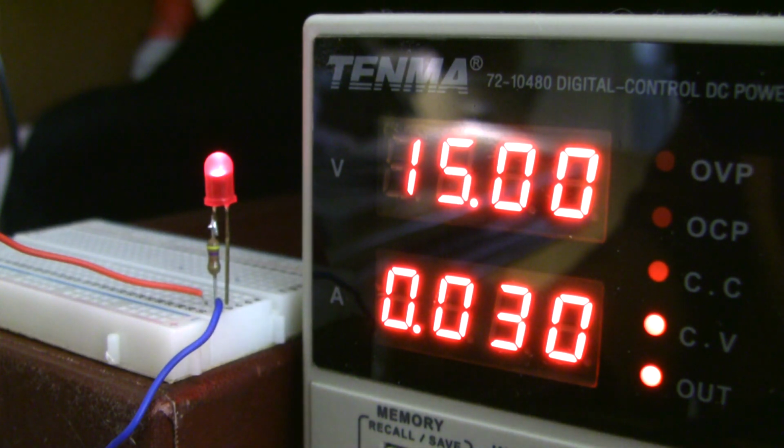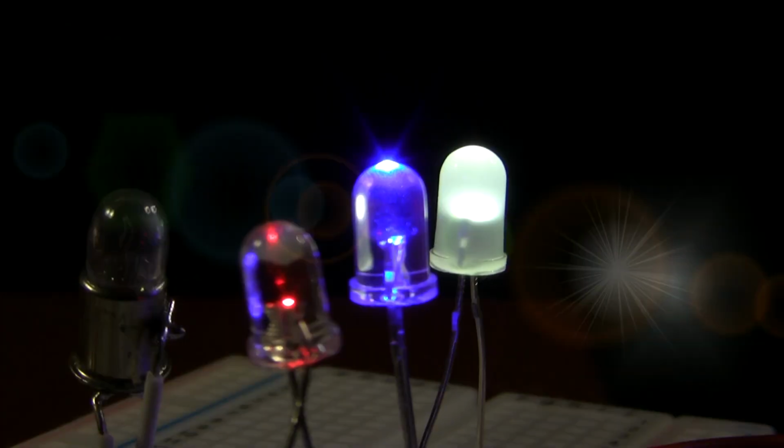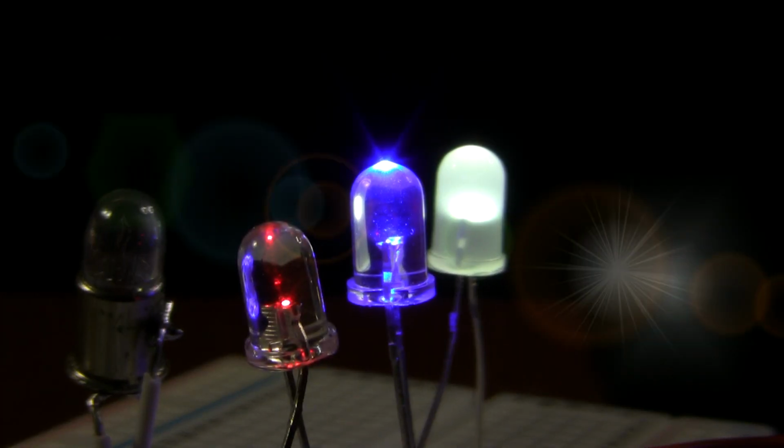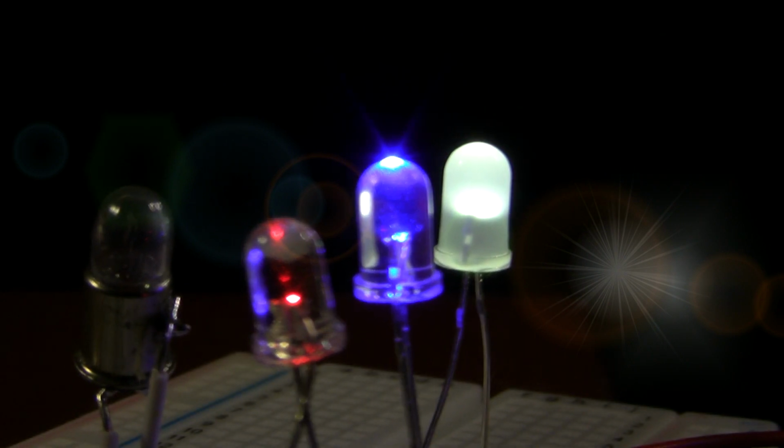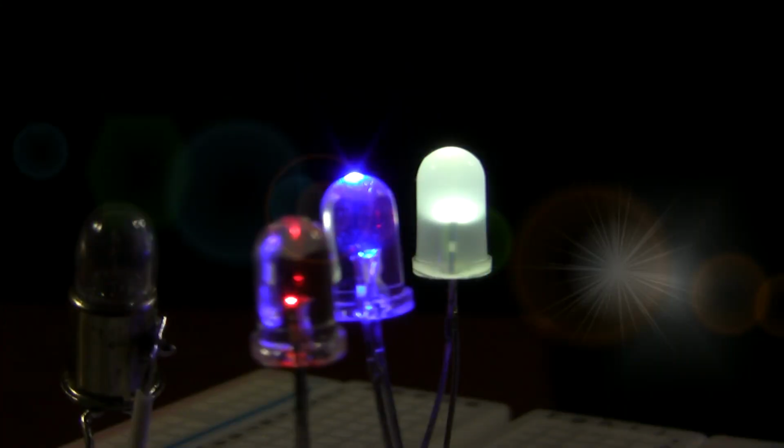Bulbs act like a resistor. The voltage applied determines the current and so the brightness. So a bulb can be made to work at a certain voltage and you can be sure that the correct current will flow because the bulb is acting like a resistor. But an LED is a diode, not a resistor. It needs to have a certain current flow to light to the correct brightness, but the current cannot be determined by the voltage applied unless a resistor is added, hence the series current limiting resistor.